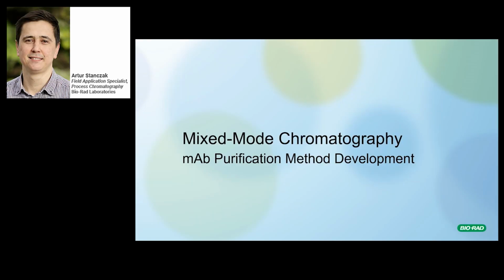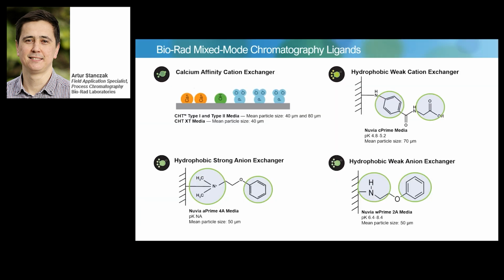Thank you, Jenaline. Now, to start, let me introduce the mixed mode resins available in Bio-Rad's portfolio. The first and very unique one is ceramic hydroxyapatite resin. It has been in use for over 30 years and has a strong track record in commercial processes. The success of this mixed mode resin comes from its unique combination of calcium affinity and cation exchange modalities. There are different versions of CHT, which vary in pore size and bead size.